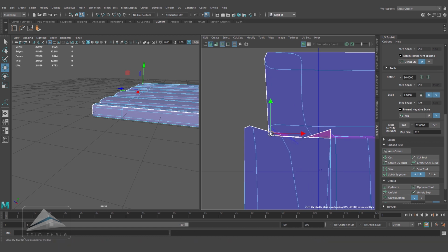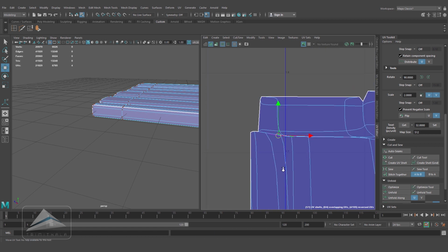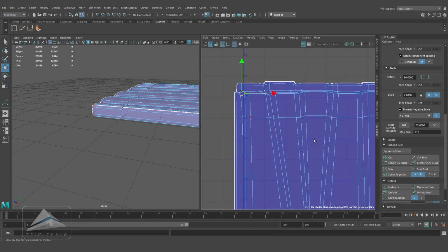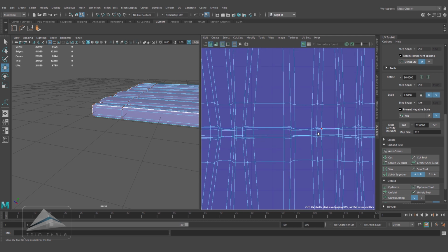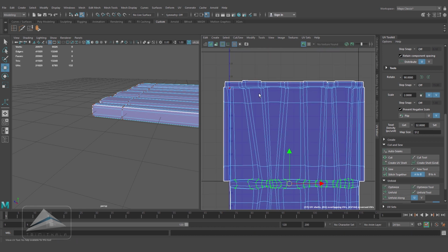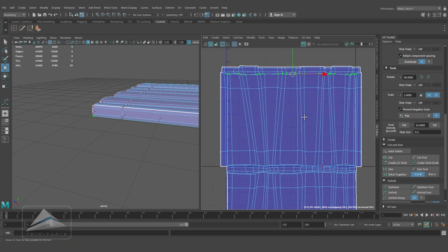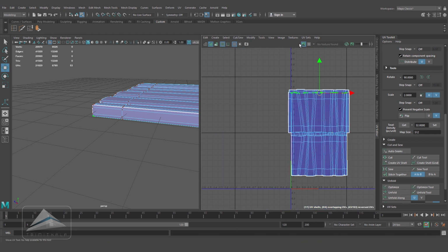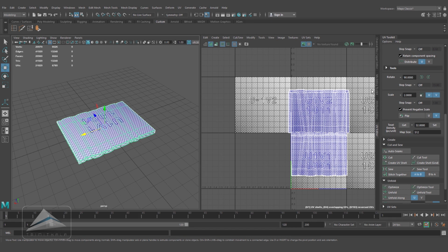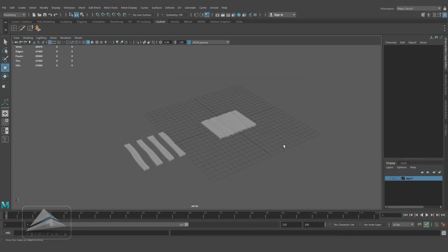I'm doing the same thing. Over here you can see some overlapping, so selecting those UVs and clicking on Unfold. Alright, so I have to check all the corners, and if the same things are there, I have to unfold it. So selecting all the overlapped areas, and I'm clicking on Unfold. Alright. Fine. So the UV shell is looking fine to me. Later on, during unwrapping, I will move all the UV shells to the positive space.